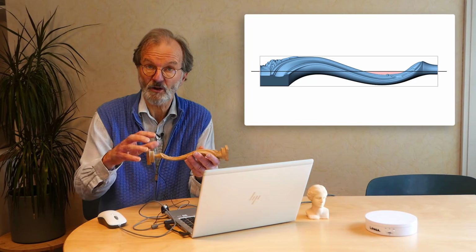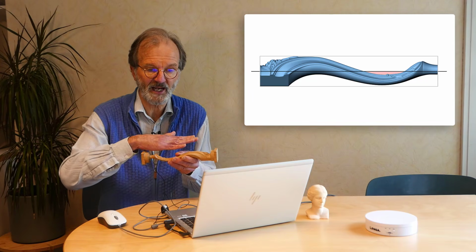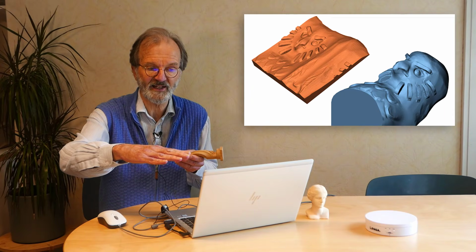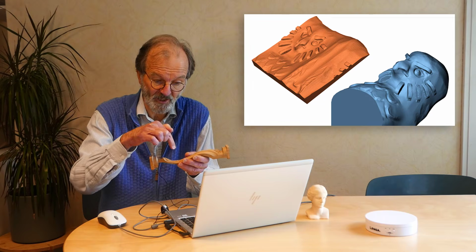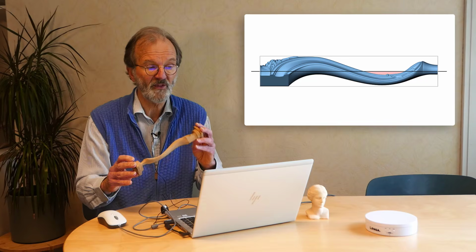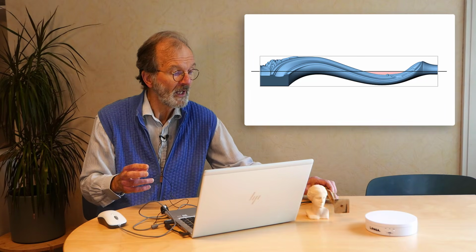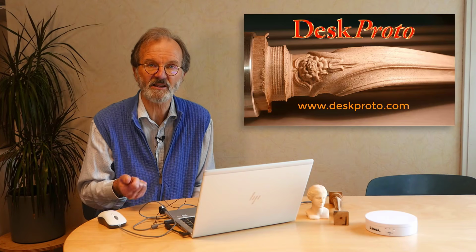Well, DeskProto allows that. Most CAM programs support rotary axis machining by using a flat relief and wrapping that around a cylinder. And with that algorithm, it's not possible to travel below the rotation axis like needed for this geometry. Well, we already created a tutorial video about that subject.